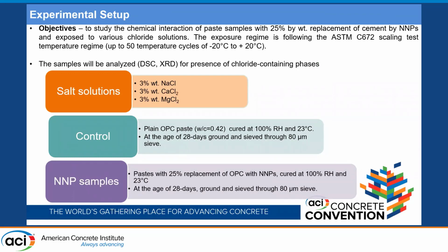We followed the exposure and temperature regime of ASTM C672, which is for the scaling test, and we held our samples for up to 50 temperature cycles.